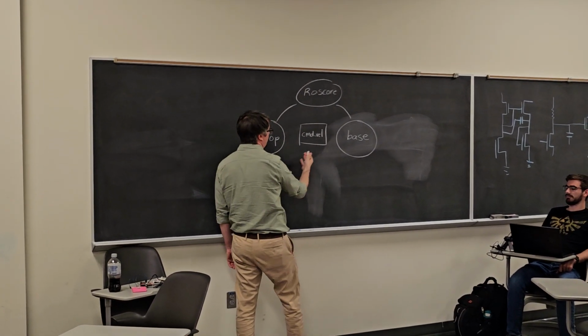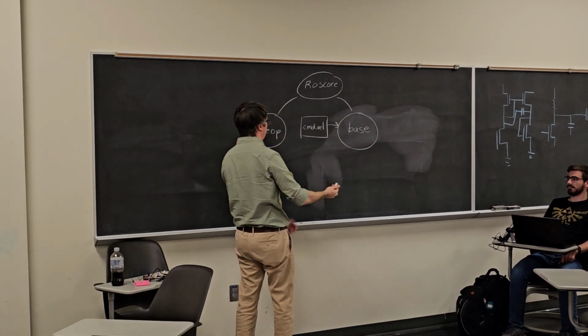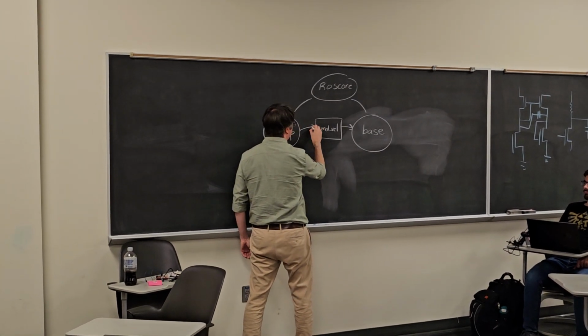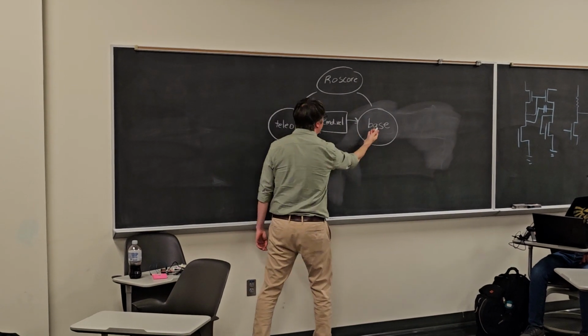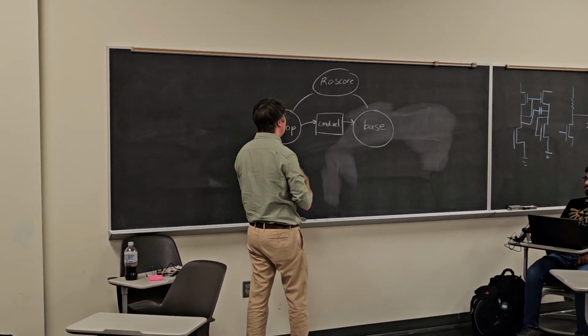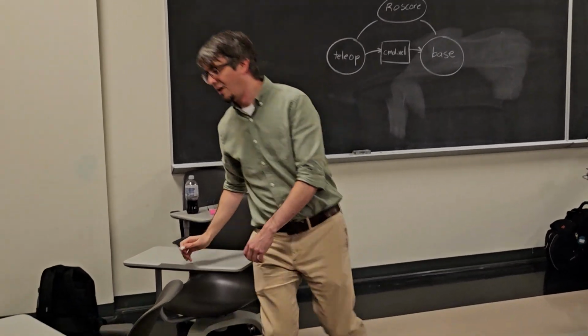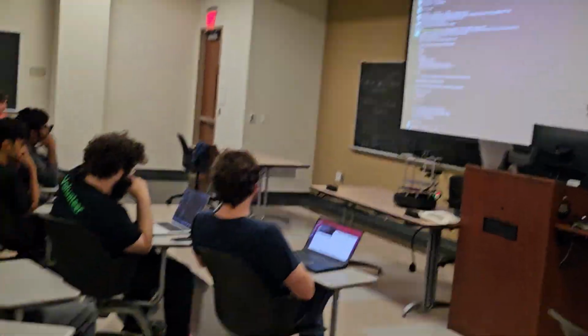Even before I started teleop, the base is subscribed to this command velocity topic, and then teleop publishes to this topic. So I give velocity commands to this topic, and the base reads from it. Every time I press one of the keys on the keyboard, we publish a new message to that topic, and then the program that is driving the base responds to it.